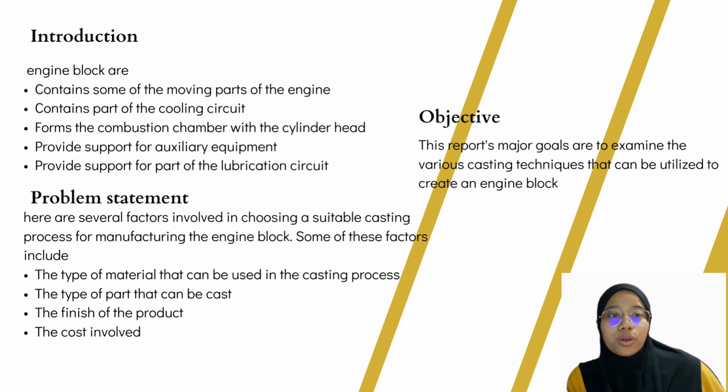Okay, for our group project, we have picked the engine block. Firstly, what is the function of the engine block? The engine block contains some of the moving parts of the engine, contains part of the cooling circuit, forms the combustion chamber with the cylinder head, provides support for auxiliary equipment, and provides support for part of the lubricant circuit.